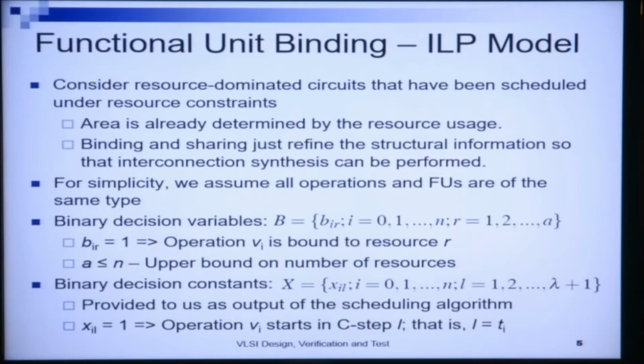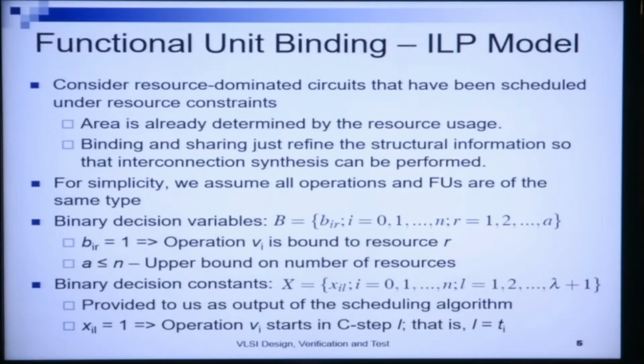By interconnection synthesis, I mean subsequent allocation and binding of subsequent resources. For example, we said muxes, buses, control units, etc. Right. So, when we have done an actual functional unit to behavioral operation mapping, then only can we solve the subsequent synthesis problems for muxes, buses, etc. Here, for simplicity, we assume that all operations and functional units are of the same type.